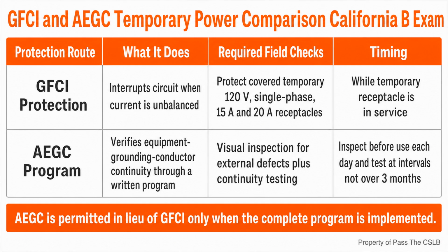I use a gatekeeper test. I ask, who installed this? What purpose does it serve? What protection applies? What can damage it? And how will it be removed? Those questions keep the general building contractor in the proper role. I do not need to perform electrical trade work to recognize a missing protective device, an illegal cord repair, a blocked disconnect, or an exposed energized part.